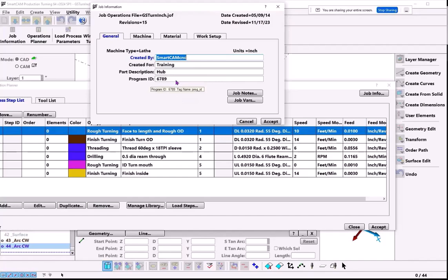I'm not sure what kind of machines you have, but the typical FANUC style code needs a four-digit number for a program ID. So at the very top of the program, it'll be the letter O and then a four-digit number that's between 1,000 and 8,999. I think FANUC reserves everything above 9,000 and everything below 1,000. So here's a four-digit number. Some people base it on a part number. Some base it on an actual program number for the number of programs they've created, whatever it is. But this can be output. You don't need it for code, but you can have it output for you.